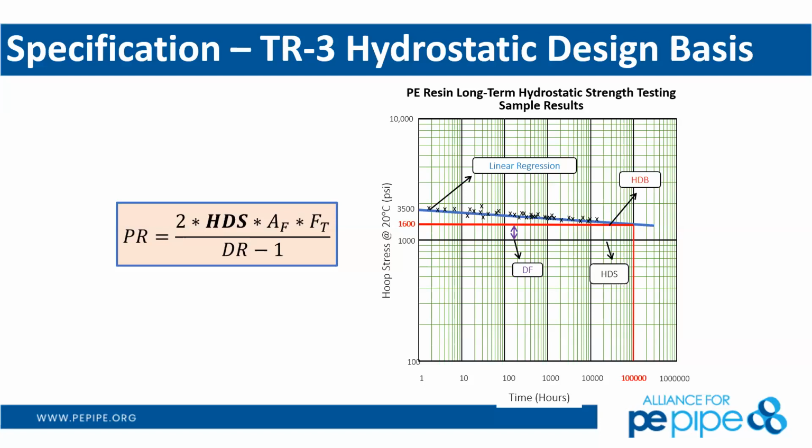If you're not on a log-log scale and you're on just a straight table with Cartesian coordinates, you'll see a very exponential type effect as you get longer term out in time. But we want to know what is the long-term capability of the product, not the short term. You can do a burst test and find something out, but the real long-term is what we're looking at.